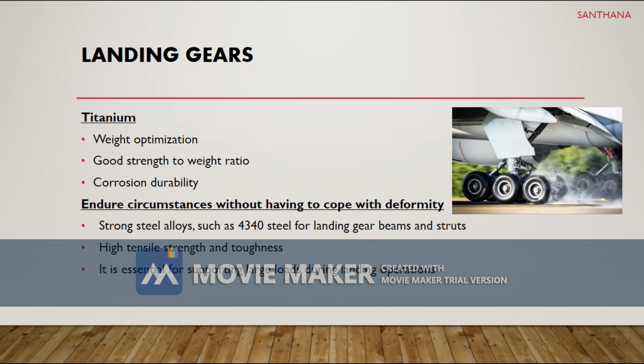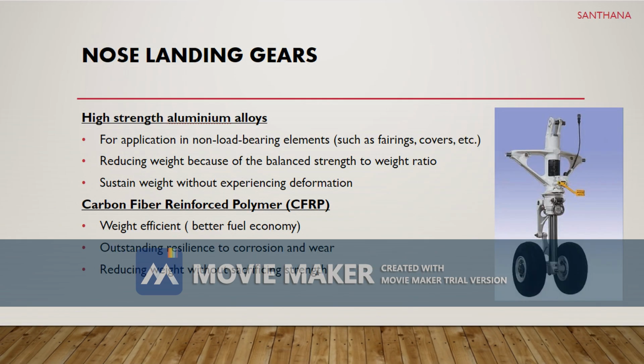Since landing gear absorbs a huge amount of force when the aircraft touches down, using a material with high durability is absolutely important for safety and performance. With the combination of titanium and high strength steel alloys, landing gear are designed to withstand immense pressure while remaining lightweight and reliable, ensuring smooth and safe landings every time.